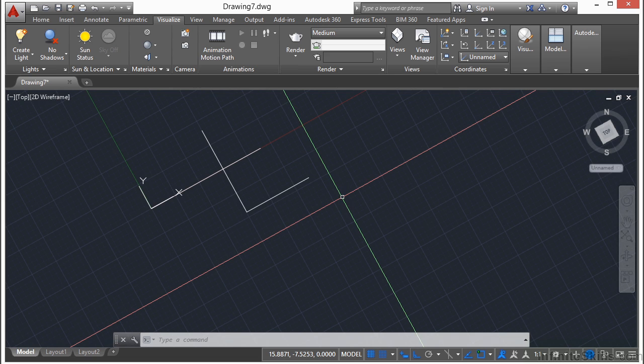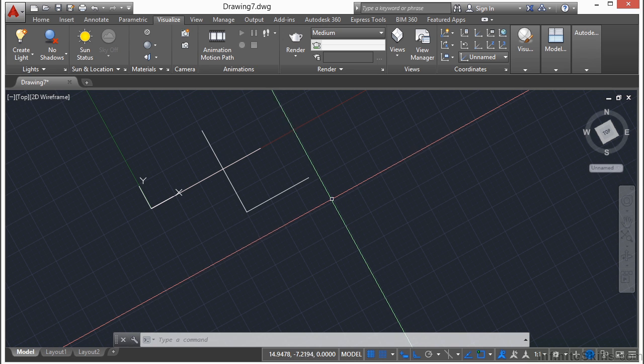Now, when you work in 3D, the UCS is key. There's a function called the Dynamic UCS feature that will automatically change your UCS to match the face of an object, allowing you to draw on that same plane as the object is selected. That's probably one of the most commonly used cases of changing your user coordinate system, when you're working in 3D. Now, that's getting a little bit heavy, of course, for this course, but it's hard enough to keep track of just 2 axes, much less 3 or 4 or 5 different coordinate systems that you might want to use. So we're going to try to keep it more simple for you in this introduction.